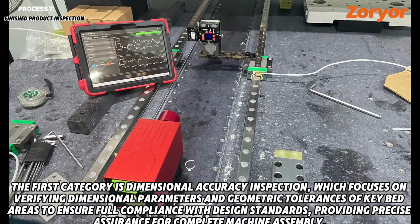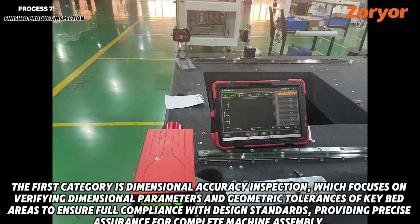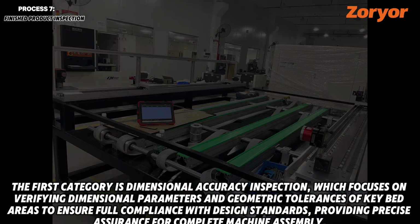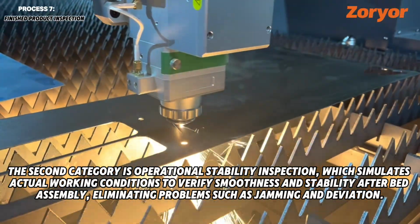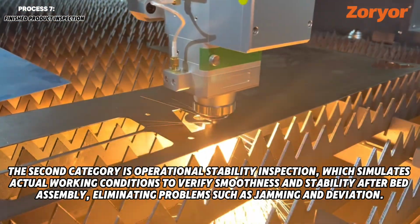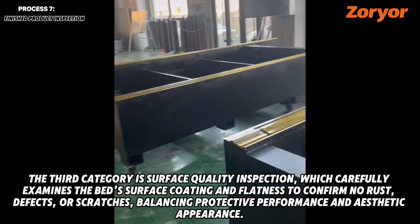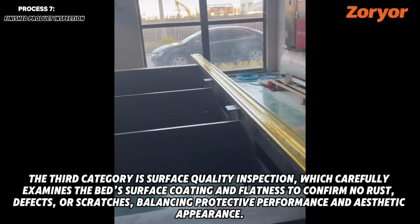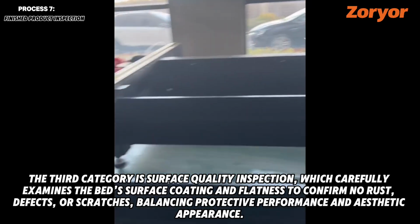The first category is dimensional accuracy inspection, which focuses on verifying dimensional parameters and geometric tolerances of key bed areas to ensure full compliance with design standards, providing precise assurance for complete machine assembly. The second category is operational stability inspection, which simulates actual working conditions to verify smoothness and stability after bed assembly, eliminating problems such as jamming and deviation. The third category is surface quality inspection, which carefully examines the bed's surface coating and flatness to confirm no rust, defects, or scratches, balancing protective performance and aesthetic appearance.